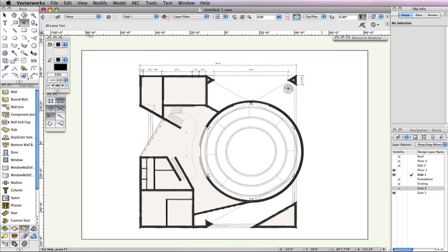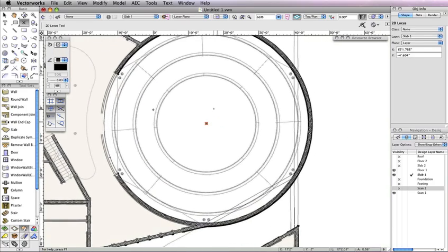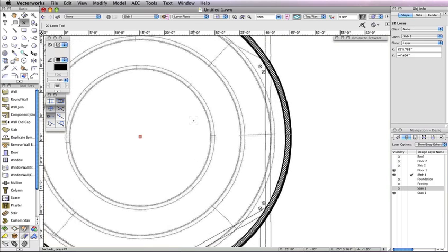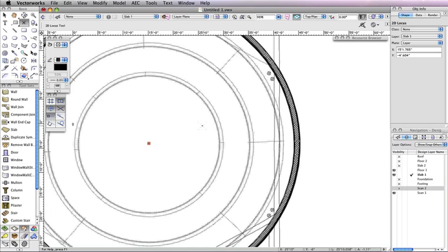Now, click at the center of the existing round wall, then the cursor cue Arc Center appears. After setting the locus point, zoom into view so that you can see the detail in the Floor 1 Scan in the auditorium. Pan if necessary so that the locus point is on the left side of your drawing area. Next, go back to the basic tool palette and select the Line tool. Then click to set the first point of the line when the cursor cue Arc Center appears.